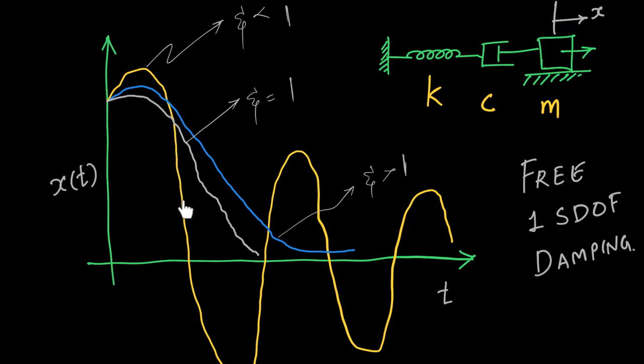Then this particular curve which you can see here corresponds to the underdamped system, as I have shown here: zeta less than 1, where zeta is the damping ratio. To put it mathematically, zeta is c by cc, where c is the coefficient of viscous damping and cc is the critical value of viscous damping for a particular system. It is given by 2 root km. So these are all additional information. These are not required for directly answering that particular question, but that's okay.